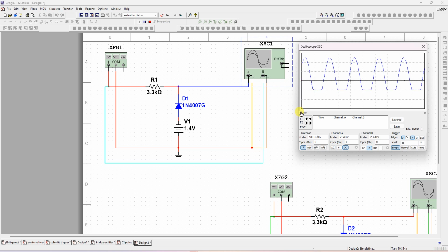So this is the meaning of a clipper circuit. This is the application wherever you want to restrict the input voltage. For example, some circuit requires minus 2, and you cannot give less than minus 2. At that time you can make use of this. Any voltages coming in below that we can remove before they enter the circuit. So this is the negative peak clipper.